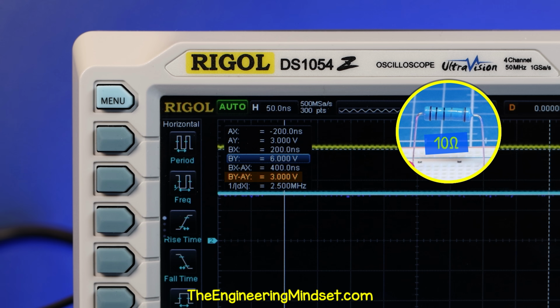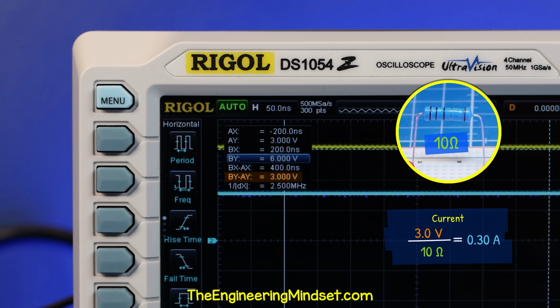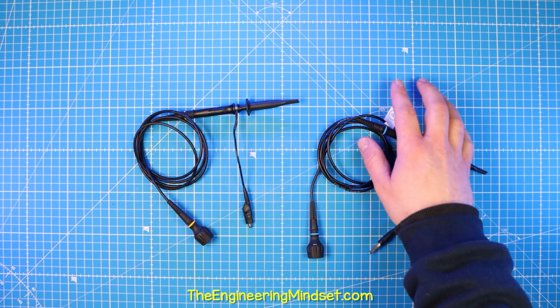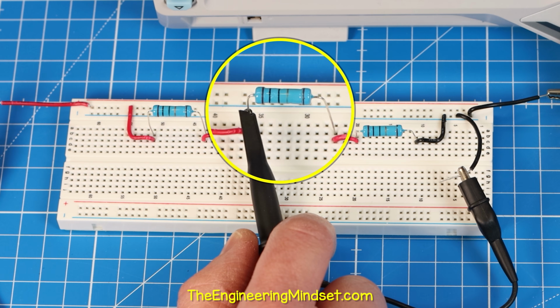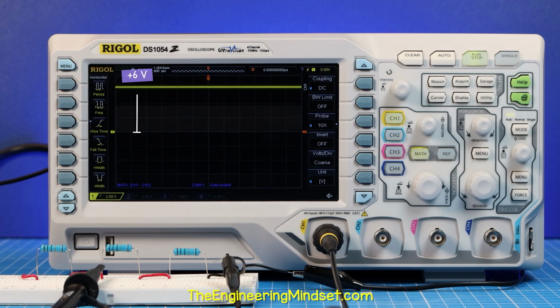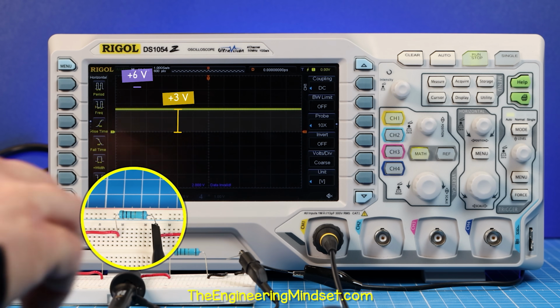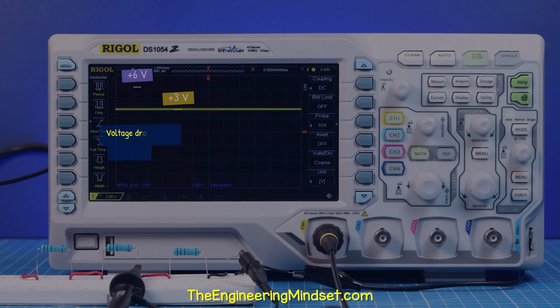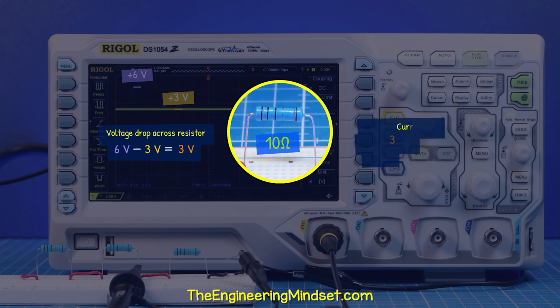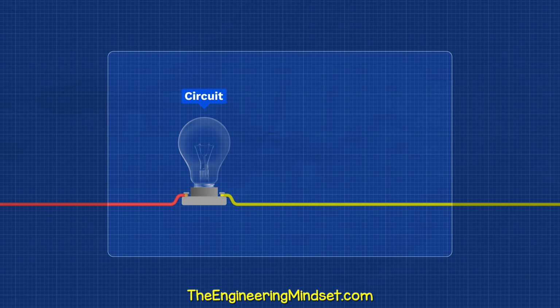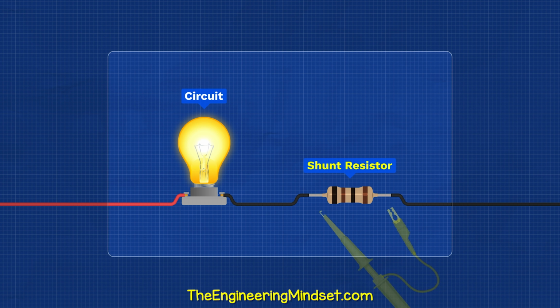Again, if we know the resistance, we can easily calculate the current. If you only have one probe, you will need to connect to one side, measure and write down the voltage value, then connect to the other side and write down the value. Then calculate the difference between them, and from that, calculate the current. Another option is to insert a shunt resistor last in the circuit and use one probe.